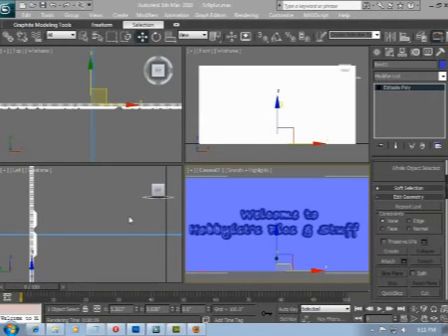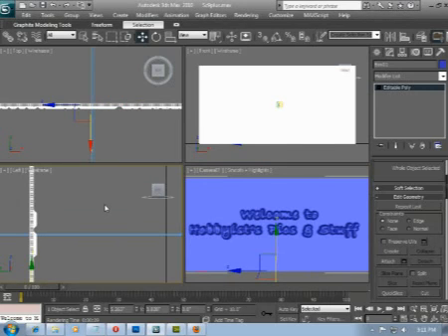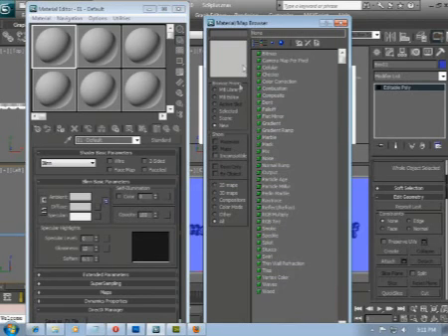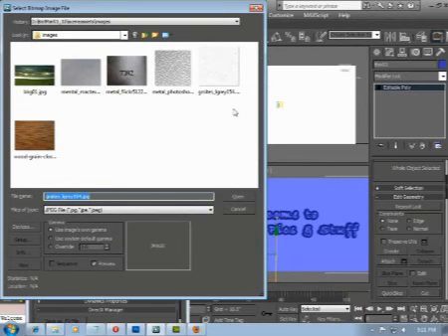So we know our output is 800 by 400, and we remember back to when we downloaded our texture swatch that it's 100 by 100. That's all we need to set up our tiling values in the material editor. So M to bring it up. The sample slot in the upper left is selected, so that one's as good as any. Standard material, Blinn shader, all the defaults. We want to click on the map button on the diffuse color channel, and then double click on bitmap in the material map browser. I put a second copy of that Elgray 154 JPEG in the Scene Assets Images folder in the current project. Let's double click that.